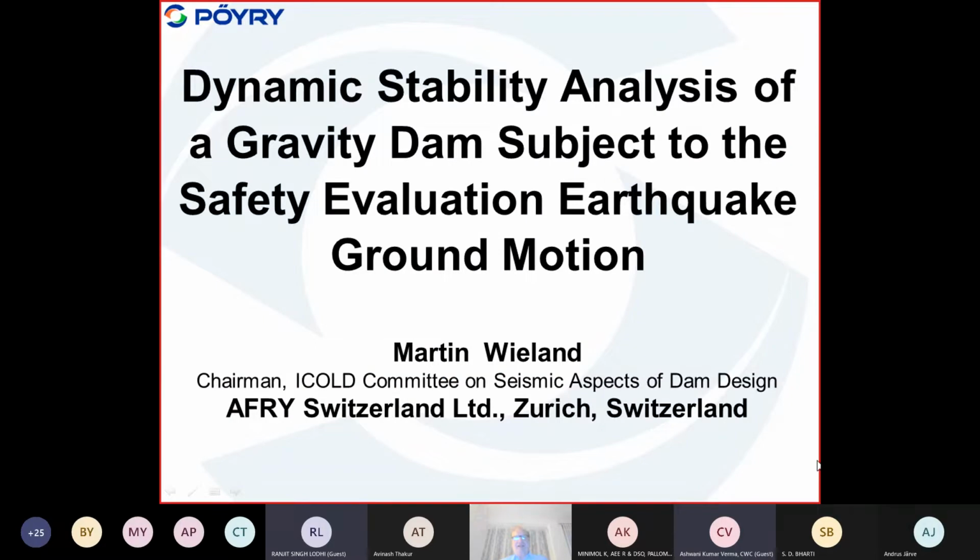Okay, and here I would like to talk about dynamic stability analysis of a gravity dam subjected to a safety evaluation earthquake ground motion. I mentioned already, okay, if we have the safety evaluation earthquake, like in India, in the Himalayas, you will get high accelerations, 0.6, 0.7 g, peak ground accelerations, I would say.